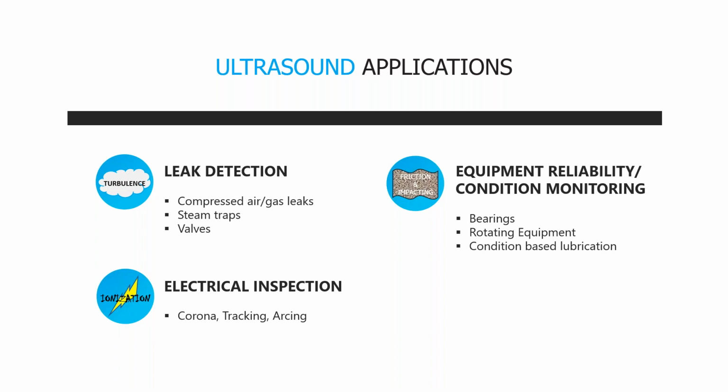So a lot of people are using ultrasound for safety-related applications, because if you do that approach, then we're greatly reducing the risk or the chance of an arc flash. But again, it's not relying solely on one technology or the other, but making use of ultrasound and infrared together, and you're pretty well guaranteed to find just about any electrical fault that may be occurring.